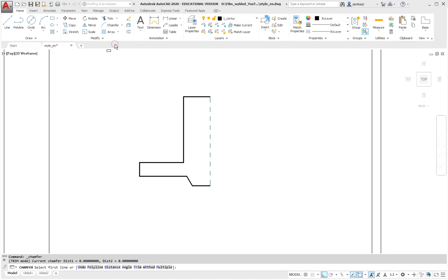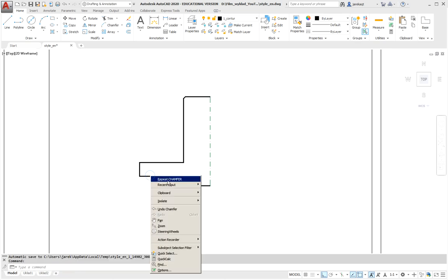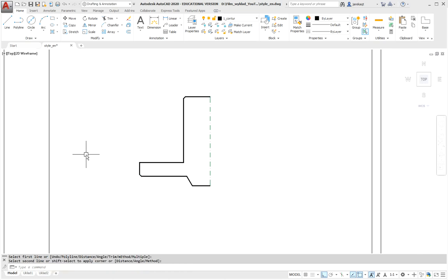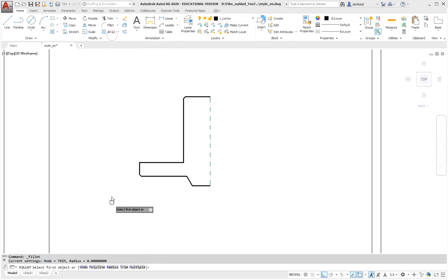Now we set the chamfer, and because the parameters are unfortunately not set because they are 0 and 0, then we will set the distance that it will be 1, and it will take exactly the same value as the second, therefore one is enough for the 45-degree chamfer. We have to do this here and repeat this chamfer with it. Here it is supposed to be a radius, so we will round it, and the radius will be 3, so you have to set it because it is 0, 3, enter, and we say it is to round.